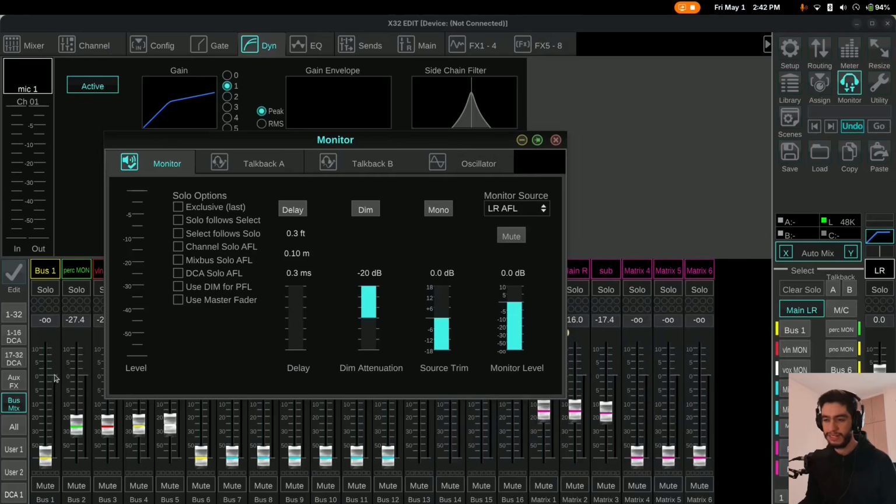But different devices have different layout of the meter, so look for the value, not how it looks. For example, the ATEM video switchers have a very big section on the top of the meters that is only 6 dB. Whereas on other meters, the top 6 dB is like a very small section. So look for the values. We're looking for -18 because that is the nominal level.